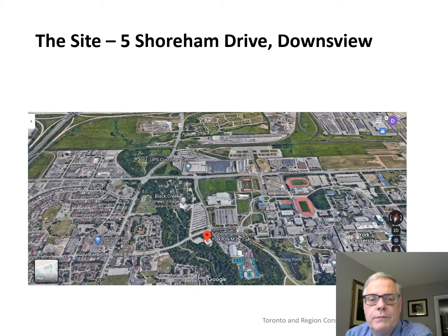Now we know that there's a major channel aquifer, a bedrock valley, going through this general area, but we weren't sure exactly where this valley was located. We had initially thought that this valley might be to the west, and therefore bedrock would be relatively close to surface, and a closed loop system would be more efficient and more economically feasible.